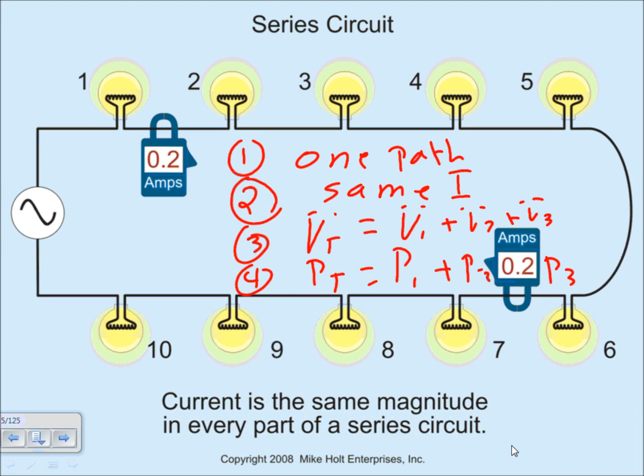The last rule that I would like to mention is 5: R total equals R1 plus R2 plus R3. If you don't know that, it's just a quick refresher. That's basically the rules of the series circuit. The disadvantage of this circuit, obviously, is that any break in the circuit will screw up the whole circuit. The worst thing that could happen is you wire your microwave, air conditioning, and everything this way. If you lose one, you lose all of them.